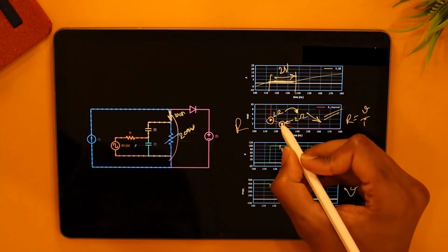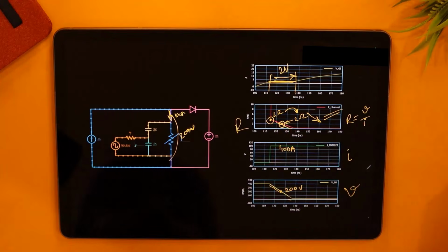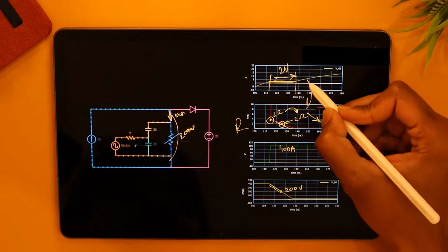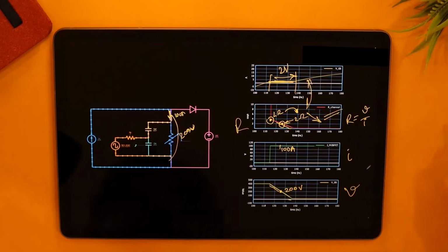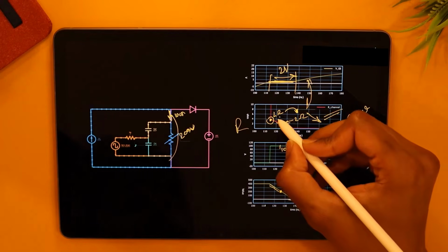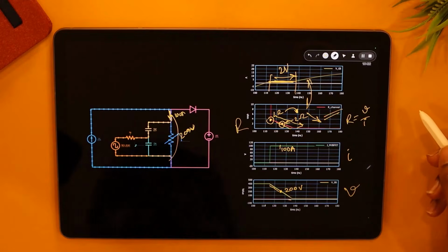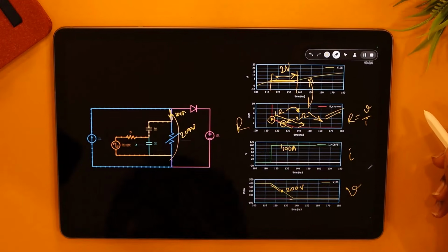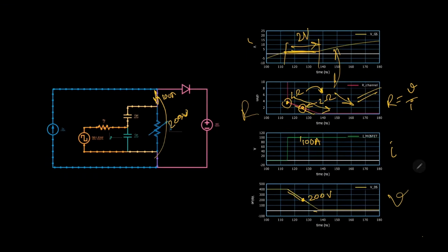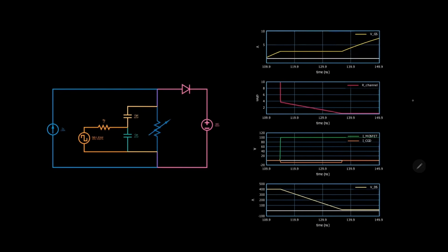And now how can you tell me that resistance is dropping and the MOSFET is turning on even when VGS is constant? This doesn't make sense. There has to be one-to-one correspondence. If resistance is falling down slowly, the VGS also needs to increase. How can it be constant, right? Doesn't make sense. So let's zoom in on y-axis of this waveform to confirm.